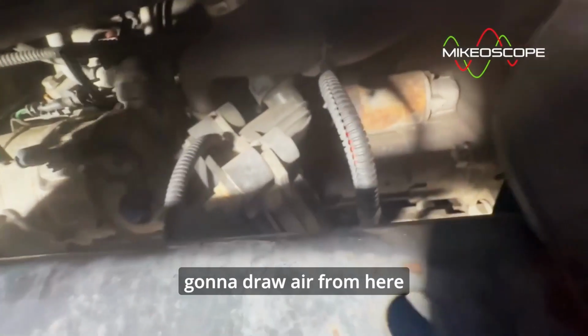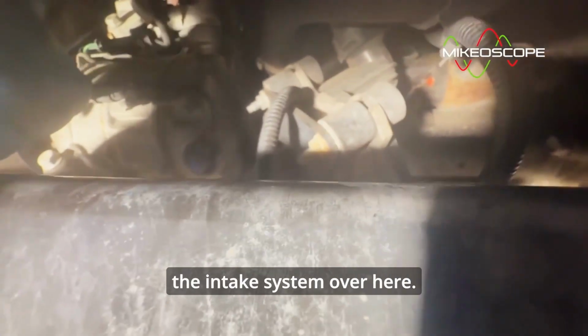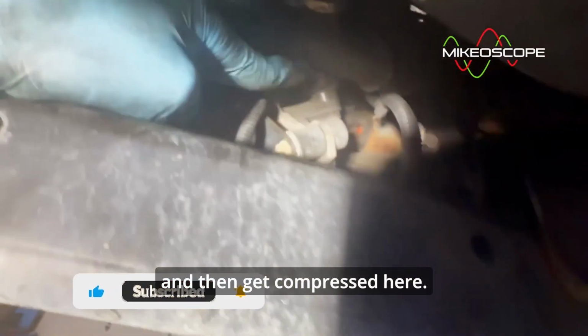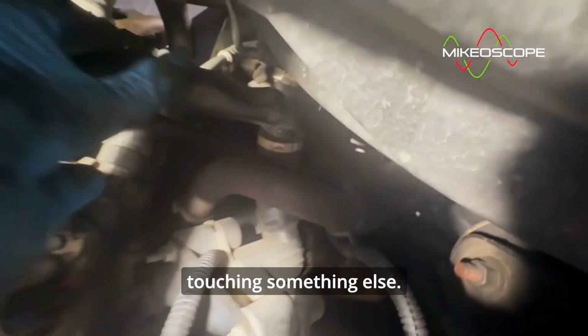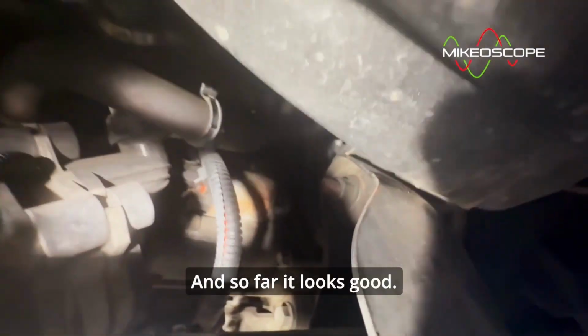That looks pretty good. Now, obviously, the pump is going to draw air from the intake system over here. It's going to come through here and then get compressed here, and then it's going to come out to this other hose, this one. So the compressed air comes through this hose here. There's a little cut here as part of the design to prevent it from touching something else, but this is the suction line of the pump, and then it's going to go through the other side into the valves. And so far, it looks good.